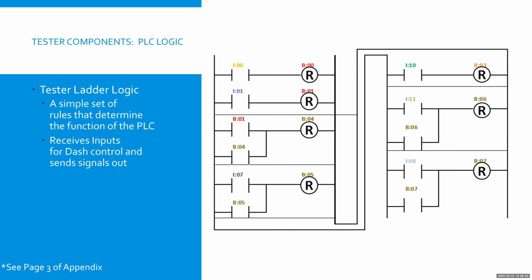Next, you operate the glow plug, and once the timer runs out, the glow plug will turn off, and another light on the indicator panel will turn on. And then finally, you hold the shutdown switch, and you turn the ignition to start, and then you release it, and then finally, the 4th light will turn on. Once all 4 lights on the interface panel on the tester turn on, that means that is a fully functional dash control unit that has passed inspection.